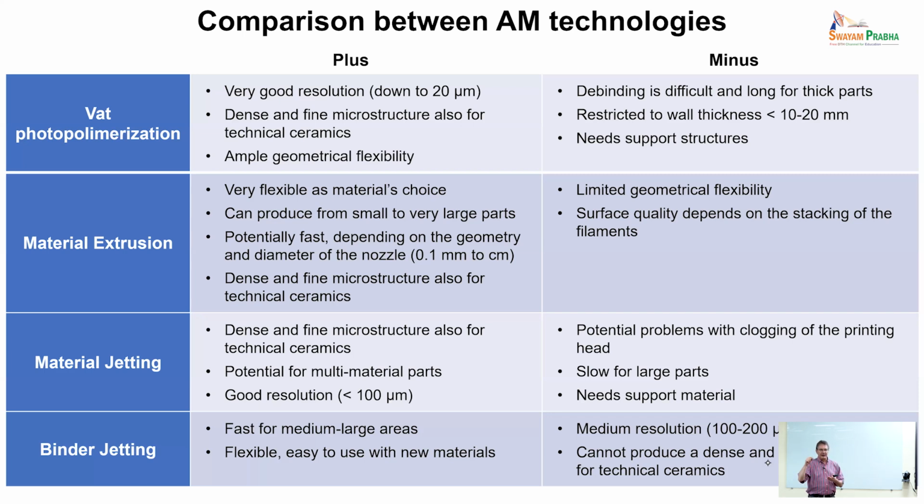You can tell the printer to stop printing, but the material keeps flowing for at least a fraction of a second. So start and stop is very difficult. Fused filament fabrication is much better from that point of view because of the fast cooling that you can achieve. You can actually do point-to-point printing with that technology.